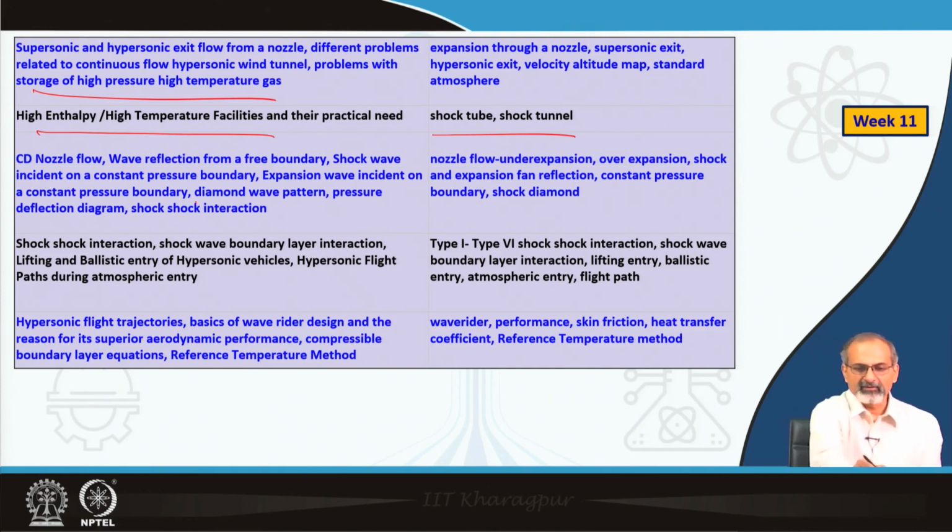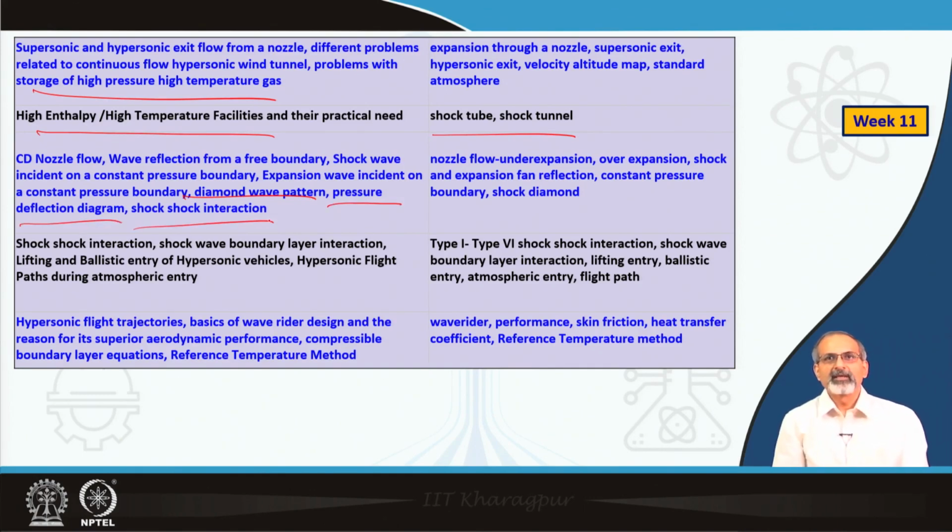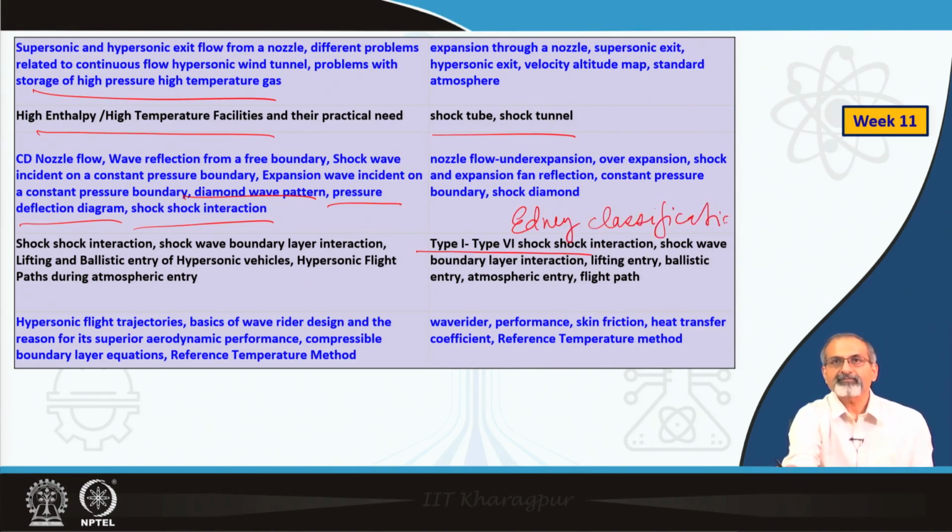These were discussed along with diamond wave pattern which may form downstream of a CD nozzle. We learned about pressure deflection diagram, and then we started introducing the shock-shock interaction problems. We learned about type 1 to type 6 shock-shock interaction according to the Edney classification.